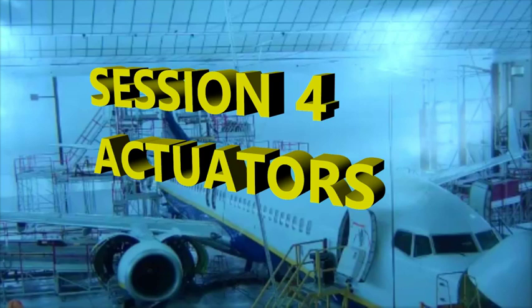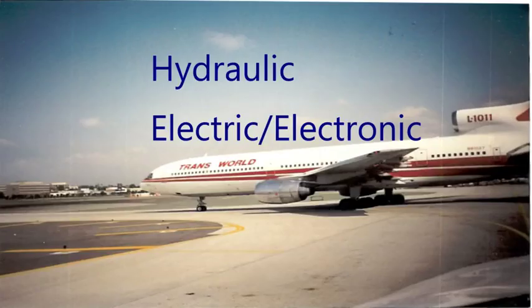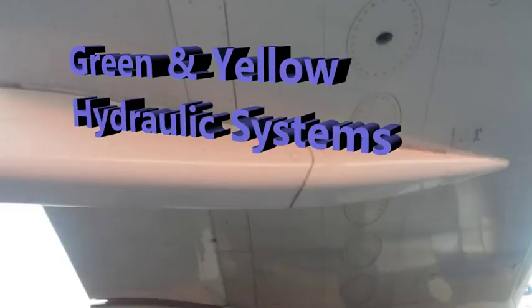We are on now to session 4 on actuators for the Airbus A350, part of the flight controls topic. On actuators, we're going to be going over the different ones regarding the control surfaces and the movement of them. As far as the actuators, they're operated two different ways, hydraulically and electronically, also electrically. So it's a combination because we have computer systems, right? We have computers. The hydraulic power used with flight controls, moving the actuators, comes from the 2 hydraulic systems that we have on the A350.